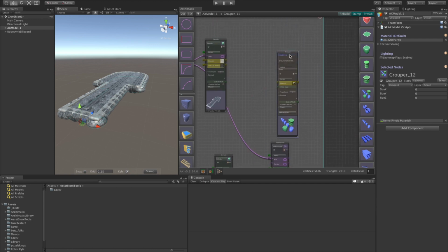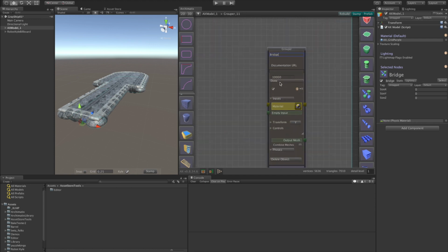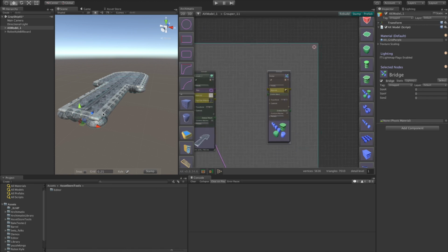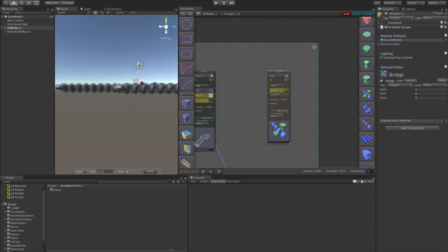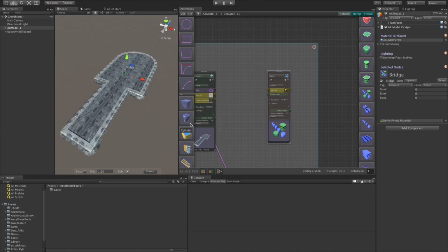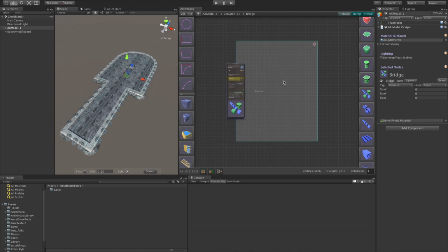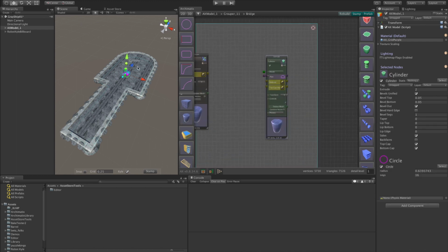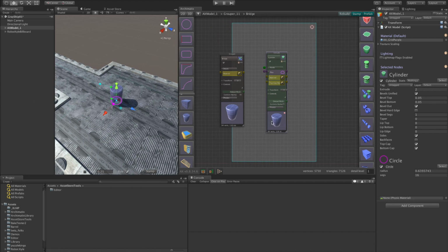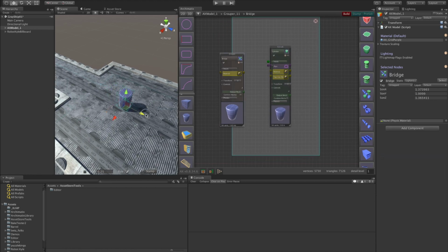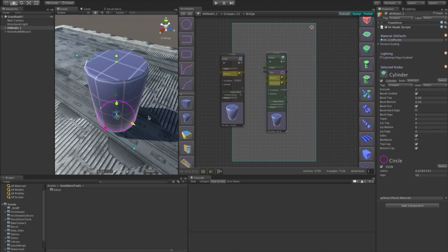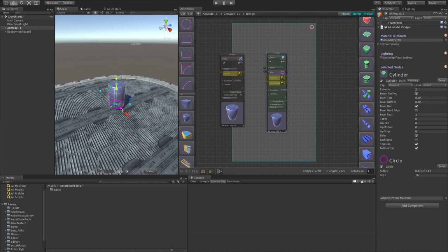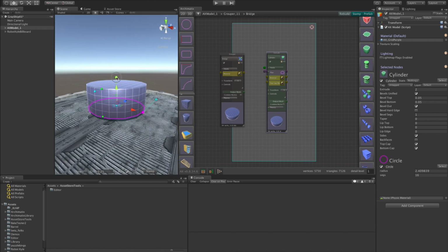We've created a new group node right inside of our old group, and I'm just renaming it Bridge. And with that group node selected, we can translate it to the front. This will essentially be our center now. So if we go inside of the group and create a cylinder by clicking on the left sidebar menu, we see that the cylinder has indeed ended up there. By selecting the group again, I can reposition it, maybe to be a little bit further up. I'll select the cylinder again and frame it, and we can begin to adjust it